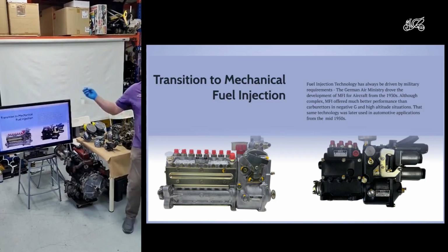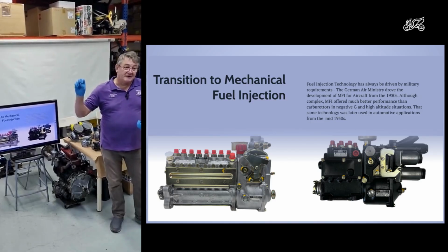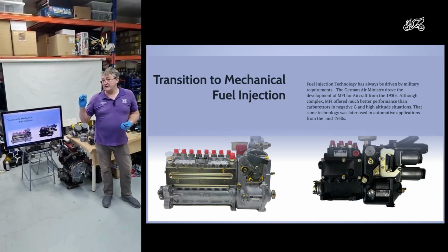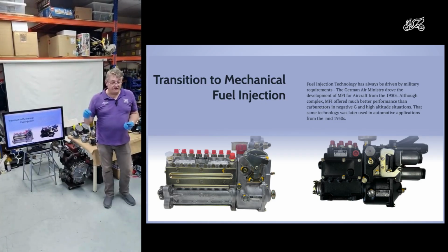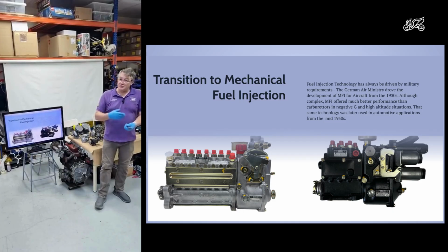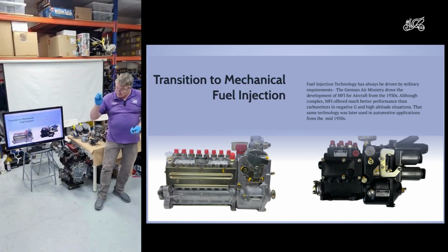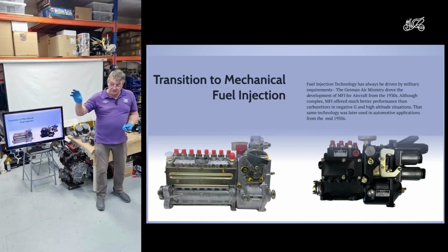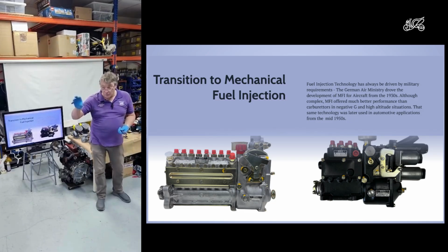When the fuel in the jet is being sprayed into the airstream, another bit of chemistry happens, which is it's cooling the charge. Just like when you sweat, your skin gets wet, and as it evaporates, it cools you. As you spray fuel into the air, it evaporates in the airstream, in the carburetor, and that cools the air.